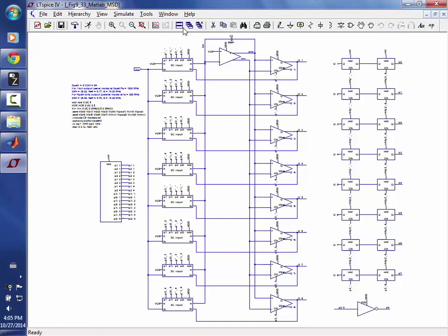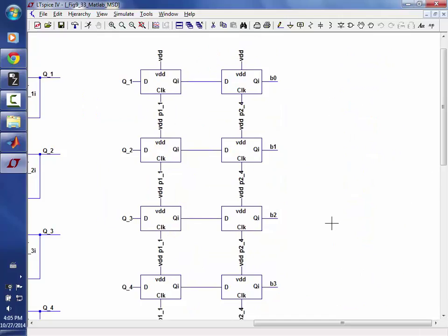On the output, the way you do the clock phasing is somewhat arbitrary. I just tried to maximize the timing margin so that when like Q1 was switching, then V1 underscore 1 wasn't. So if Q1 switches because of Q1 underscore, if they switch at the same time, then you'll clock the right value and you have one whole clock period for it to make a decision.